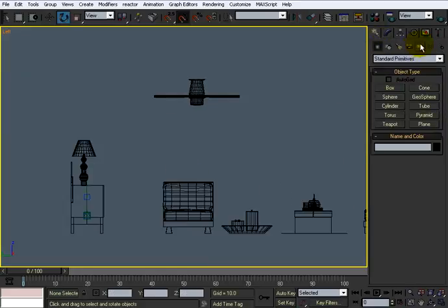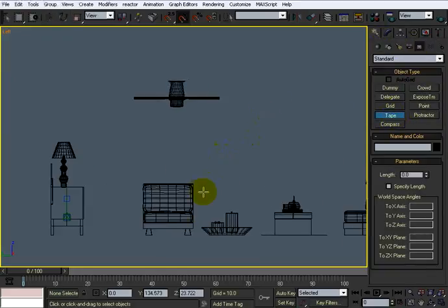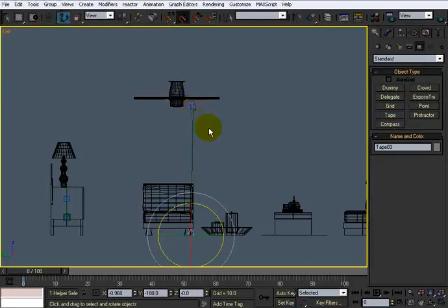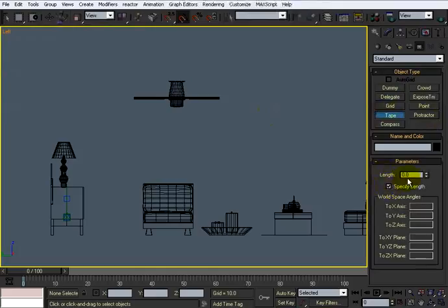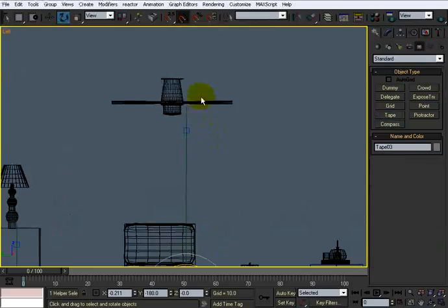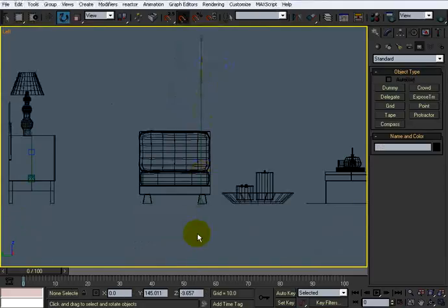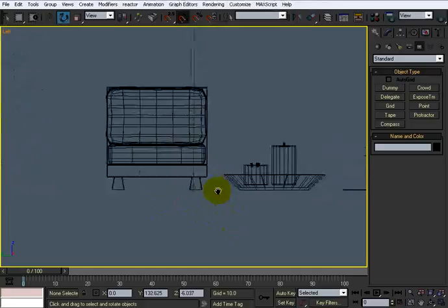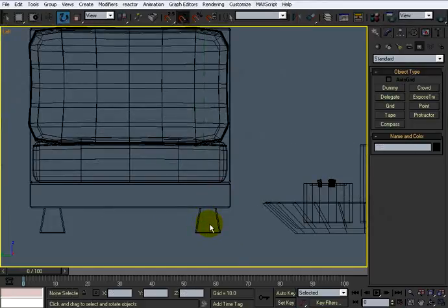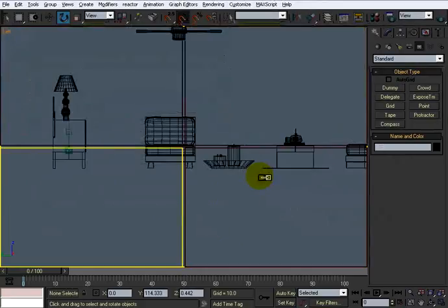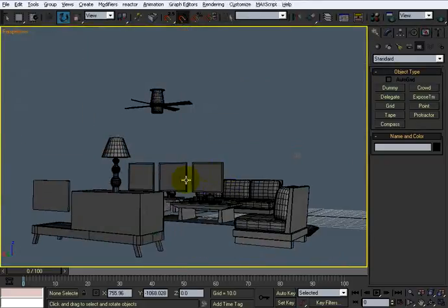And what I'm going to do is get out a tape measure here. And I'm just going to go to the bottom here to there. Delete that. I'm just going to measure up, and you see right there, from what we looked at a minute ago, it said 7-foot minimum right here for the blades, and we're just about at that. So we actually put this, without even measuring it, pretty much at the exact point it needed to be. Alright, so that's the ceiling fan right there.